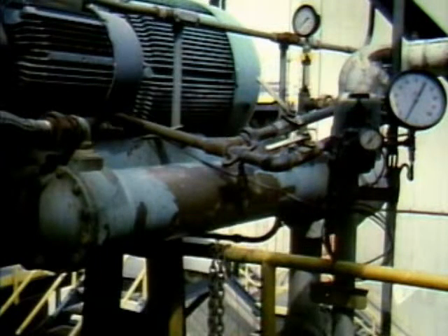On the other hand, lubricating oils are often cooled in lube oil coolers to maintain their viscosity and lubricating ability. If lube oil is overheated, its viscosity and lubricating ability are decreased. As a result, it may not adequately lubricate bearings or other components.